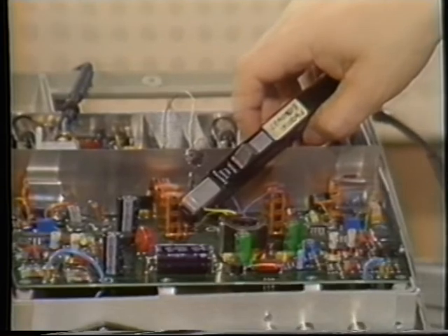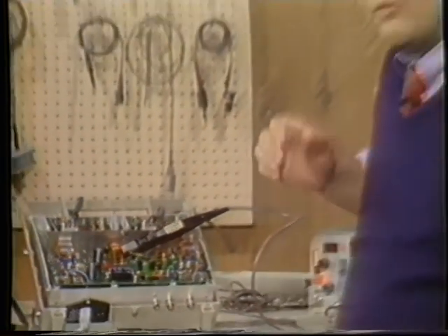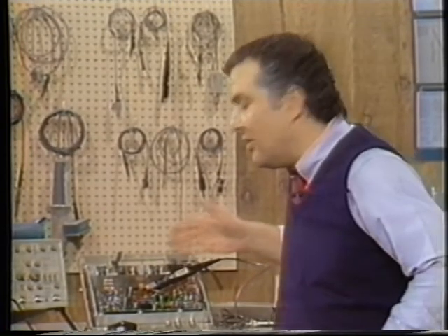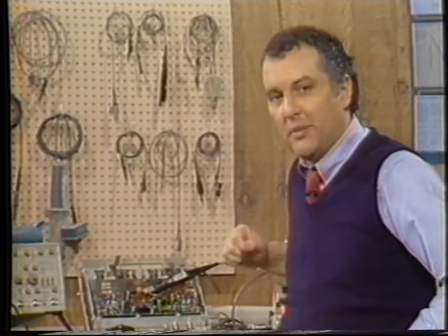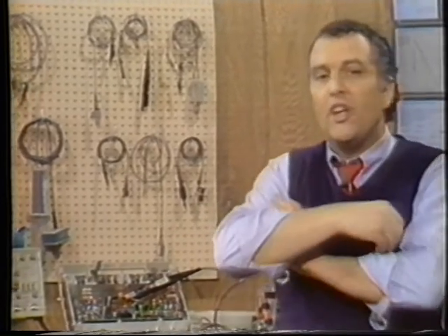Just like voltage probes, before you can select the right current probe, you have to know some things about the characteristics of the signal under test and be able to match that to the probe specifications. For repetitive signals, you need to know the maximum AC current continuous wave as well as the frequency. Current probes are bandwidth limited just like all other probes, and their ability to withstand current degrades with frequency. Remember that current probes operate by converting the circuit's magnetic field to voltage by transformer action. Current probes are sensitive to DC content because it shifts them up in their magnetization curve and could reduce their signal accuracy through core saturation.